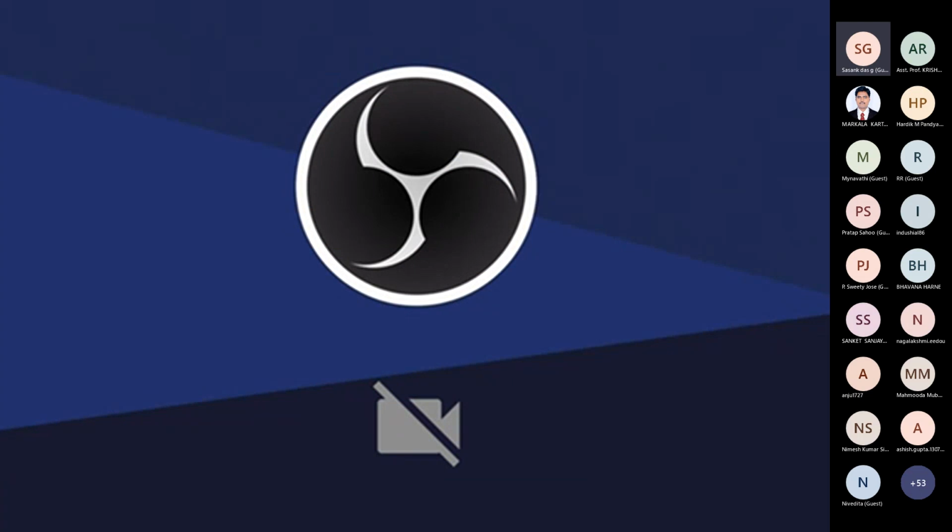Apart from induction generator, why don't we go for synchronous generators? I have mentioned some of the advantages of induction generator. The main advantage of induction generator is that no external source is required to supply the reactive power which is required for the voltage build-up procedure. So the advantage of that is that you can supply the area which is far away from the national grid. That means isolated zone. That is one of the major advantages of using induction generator.